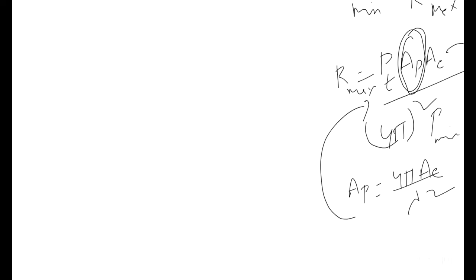Next, we will see what is happening. I will explain a rough diagram here. Transmitter section. From the transmitter it goes to the duplexer, and from the duplexer to the antenna. From the antenna it comes back to the duplexer. The echo signal in the duplexer is connected to the mixer. The mixer has two connections. See here, this is the mixer. One is the low noise radio frequency amplifier. The other is the local oscillator.